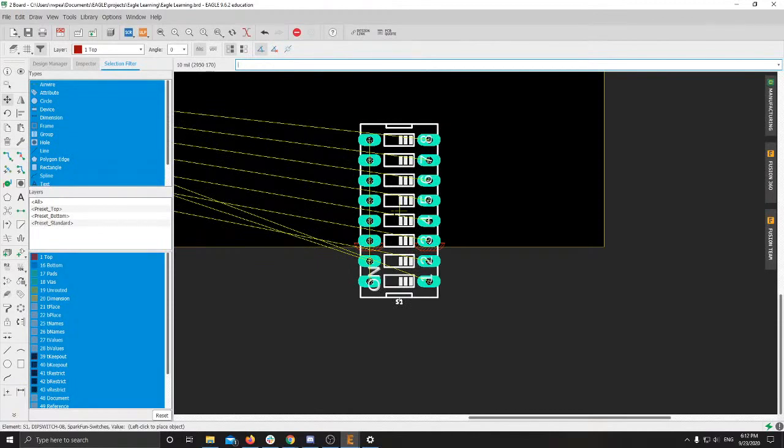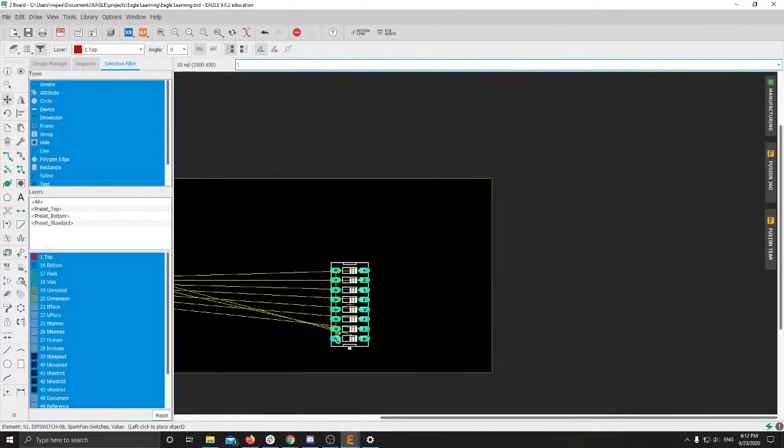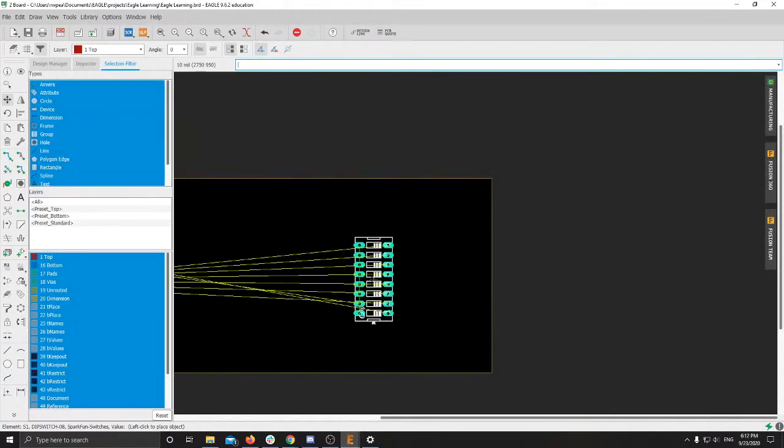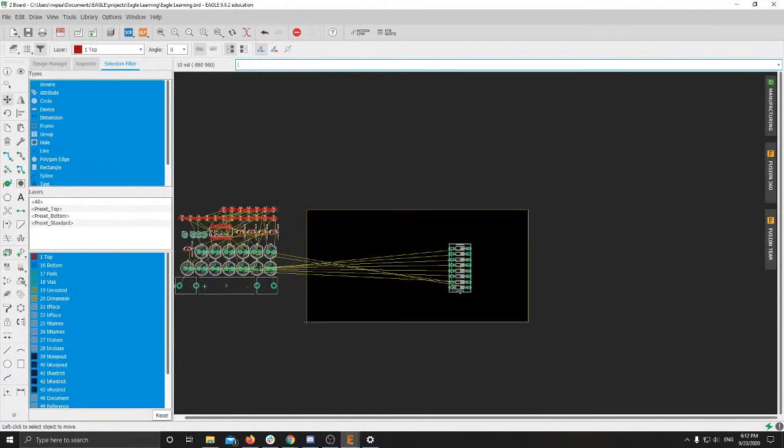What that means is that you have an actual thing of copper or a through hole too close to the edge of something or to another component or a hole, and it means that based on the rules that you've configured Eagle with, which you're just using the default one and you don't need to worry about that right now, it essentially means that it's too close and that it might not be manufacturable and that you told Eagle to watch out for that and it's checking it for you. So I'm just going to place that right around there.